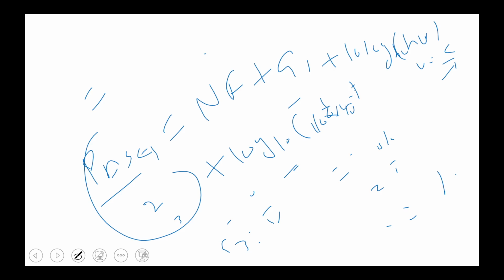Now you have to calculate, given the bandwidth of the amplifier, the signal to noise ratio, the optical signal to noise ratio of the fiber. So you have to take the signal power minus noise power in dB. Your noise power you have already calculated through the noise power spectral density, and you have to calculate only the signal power.